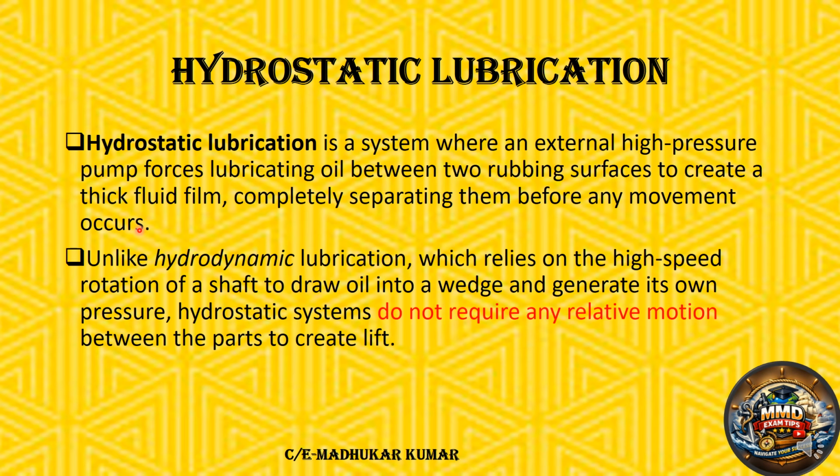But what happens in hydrodynamic lubrication? Basically, it relies on the high speed rotation of the shaft. The shaft starts rotating, draws in the oil and forms a wedge. Due to the wedge formation, it generates its own pressure and separates the rubbing surfaces. But the hydrostatic system does not require any relative motion.